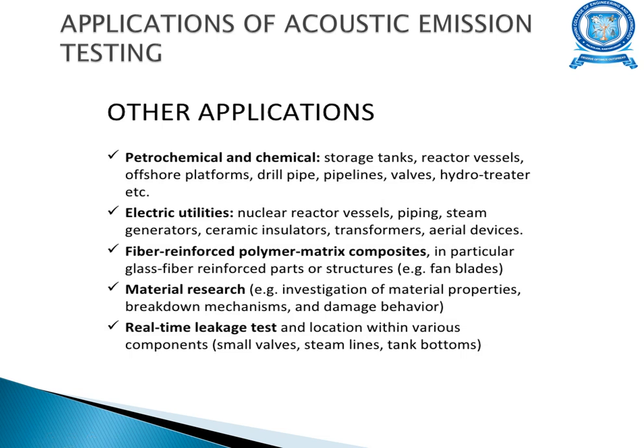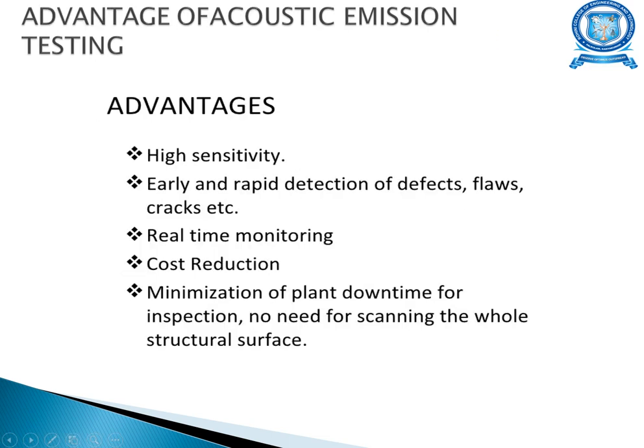Fiber reinforced polymer matrix composites, particularly glass fiber reinforced parts or structures, for example fan blades, are tested using this acoustic emission testing. It is also used for research of materials, for example material property investigation and breakdown mechanisms. And for real-time leakage testing and location within various components, such as small valves, steam lines, and tank bottoms, you can go for acoustic emission testing.